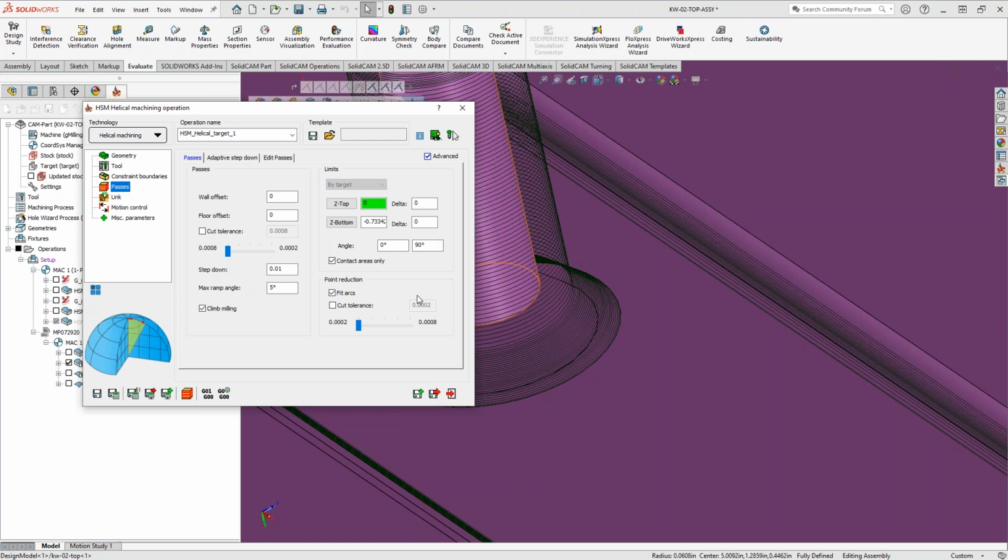Yeah, when you get started with these combination toolpaths, you will get the option for one to do a step down, as well as an additional one for a step over. So like Mark was saying, between 0 and 45 degrees, it would be a step over. And then the step down would be from your 40 to 90 degrees.